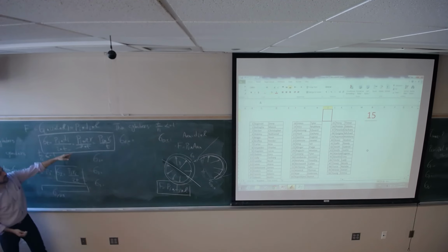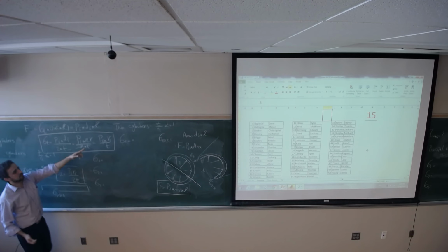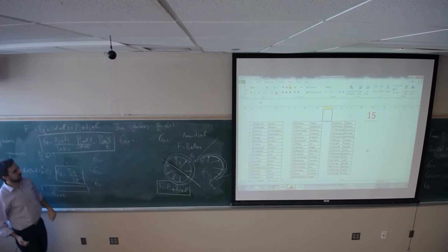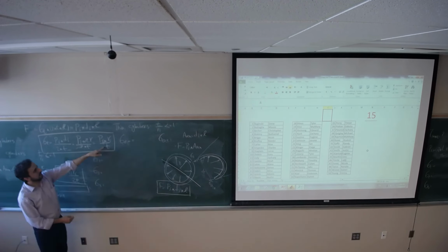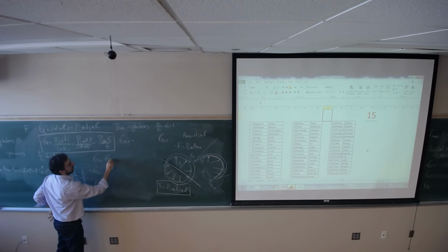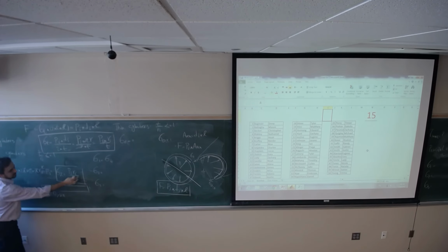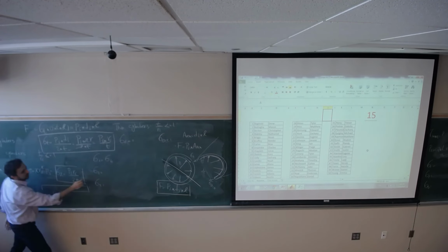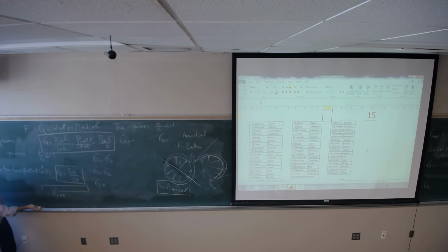So the greatest is going to be this one, because p is always positive, r is positive, thickness is positive. So we have tensile stress for the tangential, and it's greater than this. So sigma 1 is the greatest, which is sigma T. The second one is still positive, but smaller than this, so sigma Z. And sigma R is 0.